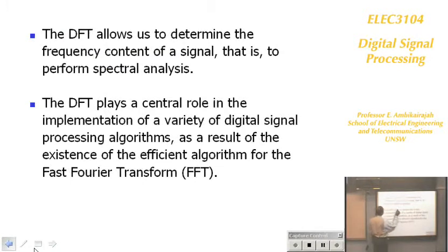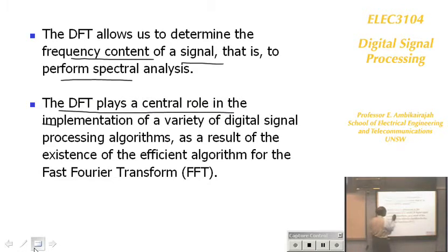DFT allows us to determine the frequency content of a signal, that is, perform spectral analysis. DFT plays a central role in the implementation of a variety of digital signal processing algorithms. And the efficient algorithm of DFT is FFT. So, summary. Okay, you've got a discrete sequence. You want to find out what frequency content it has.